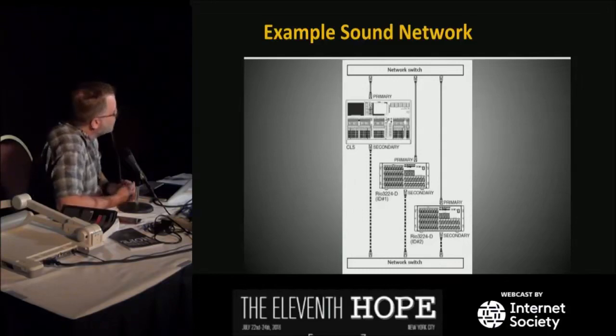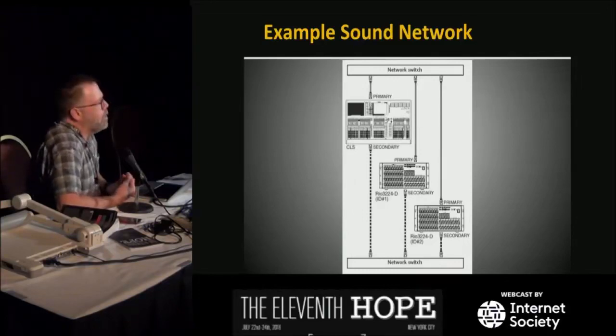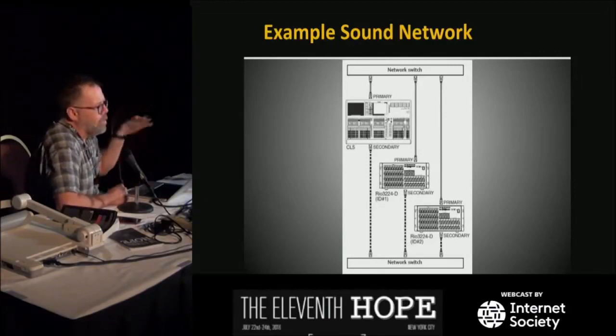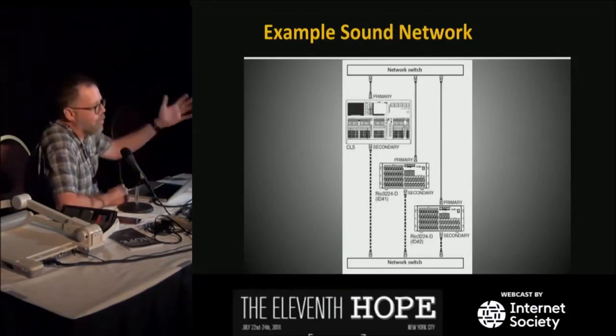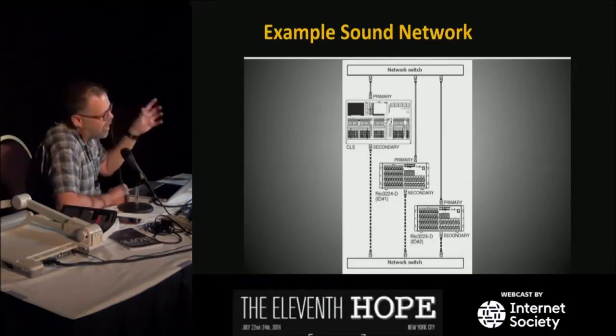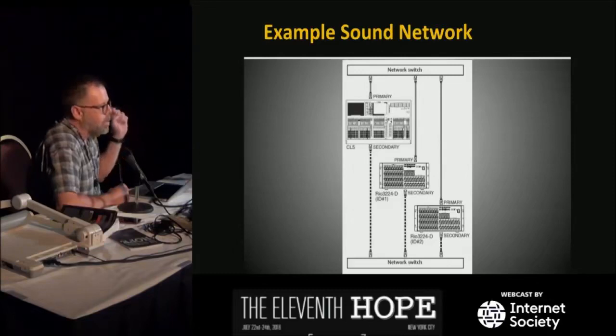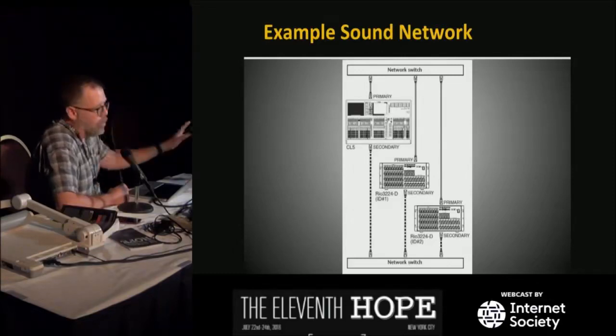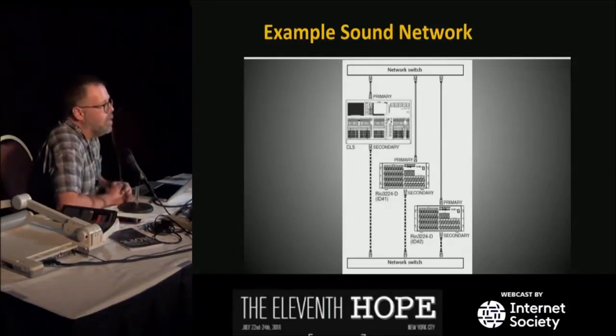So a lot of applications that would try to transmit audio or video and have not a robust transmission medium would just buffer the hell out of it. That doesn't work for us. If we have in-ear monitors on a performer, we need to be less than 7 or 8 milliseconds, or else they're going to perceive it as an echo and throw their in-ear out on the floor, and freak out. So we don't want that to happen.